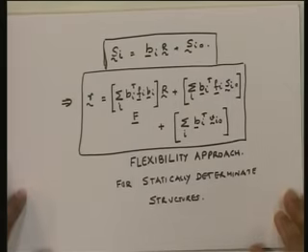Okay, so what you have in here is that we have set up how to get the member forces as well as the joint displacements using the flexibility approach. Okay, but this essentially, if you look at it, is true for a statically determinate structure, because we said that you can actually solve for Si given the loads.